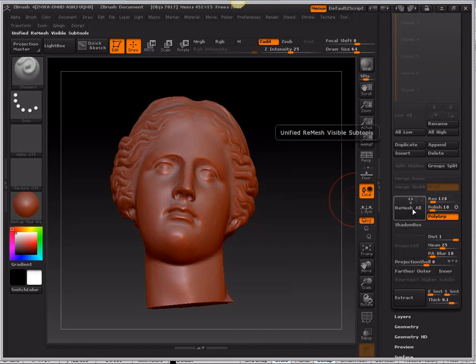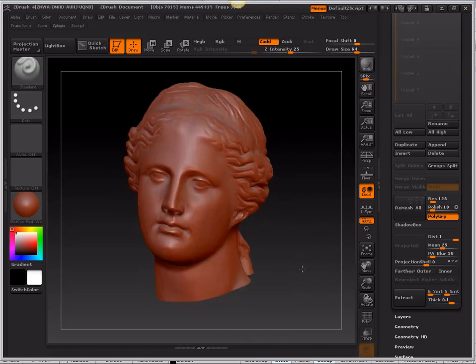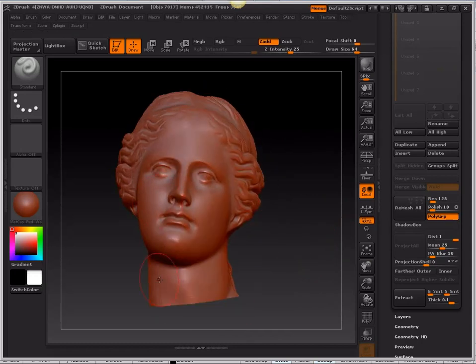And we're going to go down into the Remesh button in the subtool toolbar, and right away there's some axis constraints that we want to turn off. This is an asymmetrical model. We're not going to be using any of the symmetry tools. And for purposes of this tutorial, I'm going to bring this sample way down, and that'll become clear a little further down.